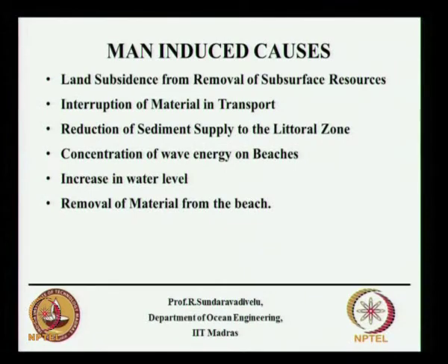The man-induced causes: this is land subsidence from removal of subsurface resources. So we have this heavy metals concentration on the sea coast, say they dredge the sand. Then the interruption of material in transport, that is construction of breakwater. Reduction of sediment supply to the littoral zone, I will explain littoral zone in one of the slides.